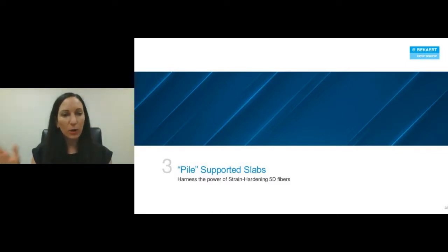All right, enough about those. Let's get into some more structural applications that we're all here for. So I have pile supported slabs, and I have pile in quotation marks. This is to cover all manner of soil improvement, right? So this could be rammed aggregate piers, helical piers, CMCs, whatever the actual soil improvement approach that you're using. I'm loosely generalizing all of them as piles.